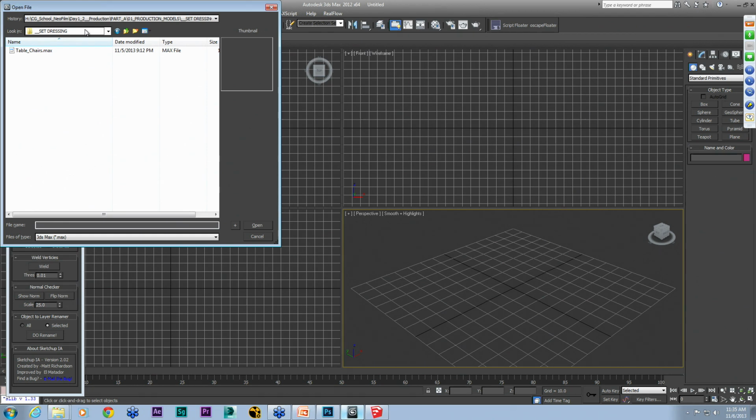Revit has some ties into Max, so you tend to get a little bit of a cleaner import. The only problems we've ever really had with the Revit files are the empty nodes and the block hierarchies that can come in from Revit into Max.